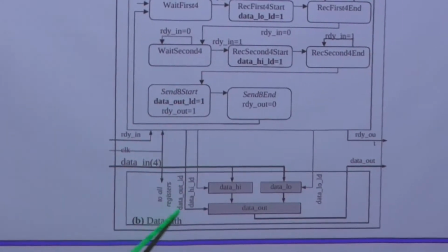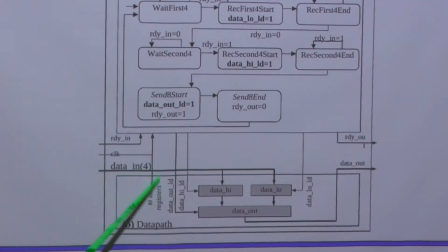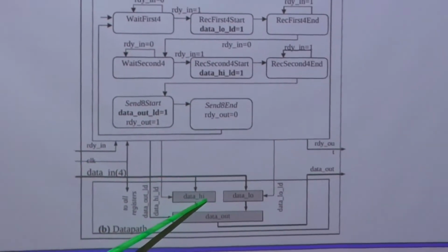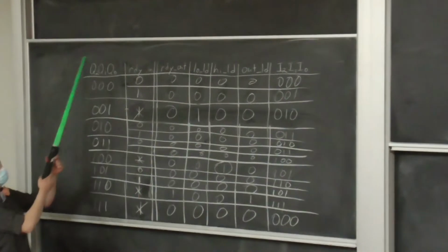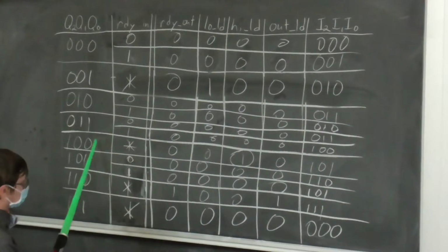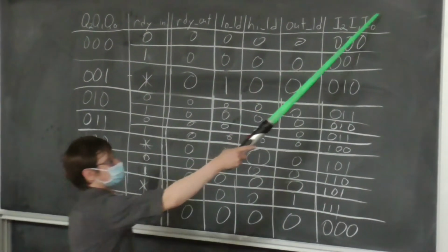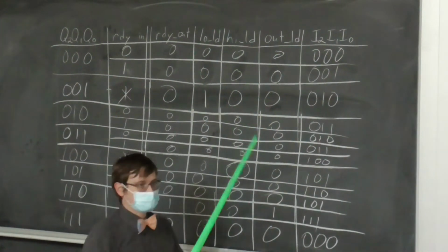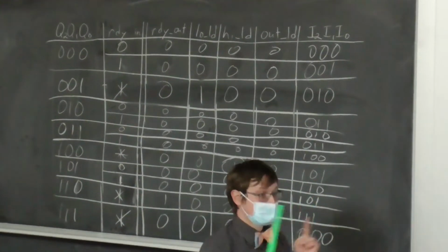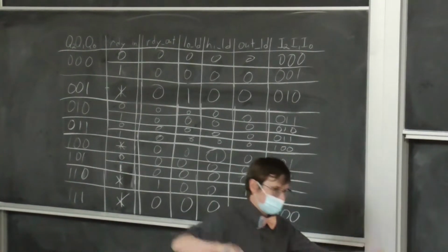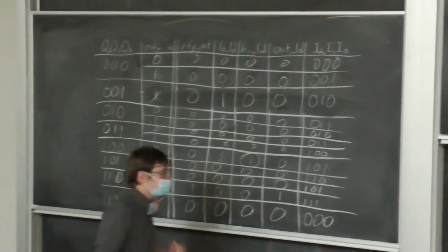Those are the intra-IC communication, right? One combinational circuit communicating with the other. In addition to that, we have the state register, which tells us which of the bubbles of the finite state machine we're currently on. And we have the inputs into the state register, which tell us what the next state is going to be on the next clock signal, or on the next rising clock edge, right? Because everything gets loaded according to the clock.